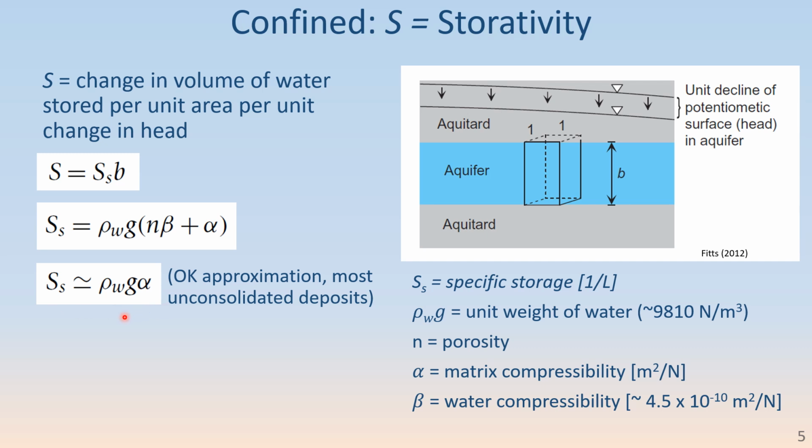In Anaqsim, you can input either S for storativity, or there's an option for inputting specific storage, which I like to do because that means your input parameter is only a material property and it's not a function of saturated thickness B.